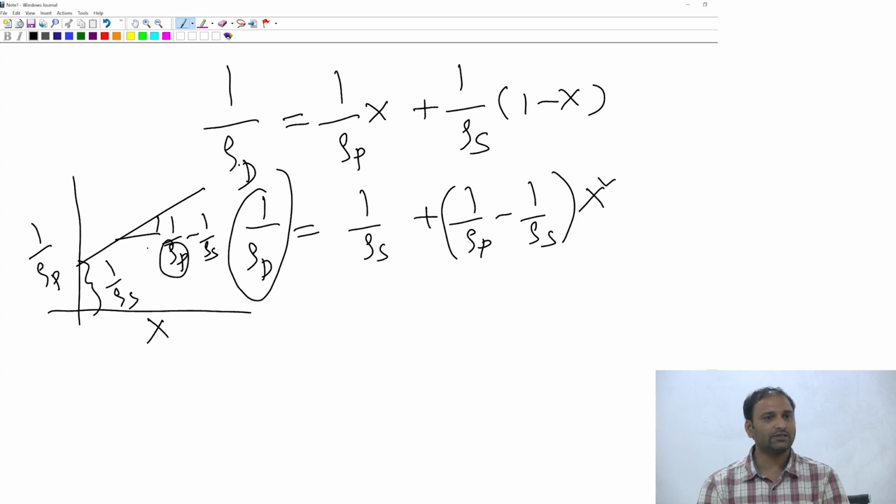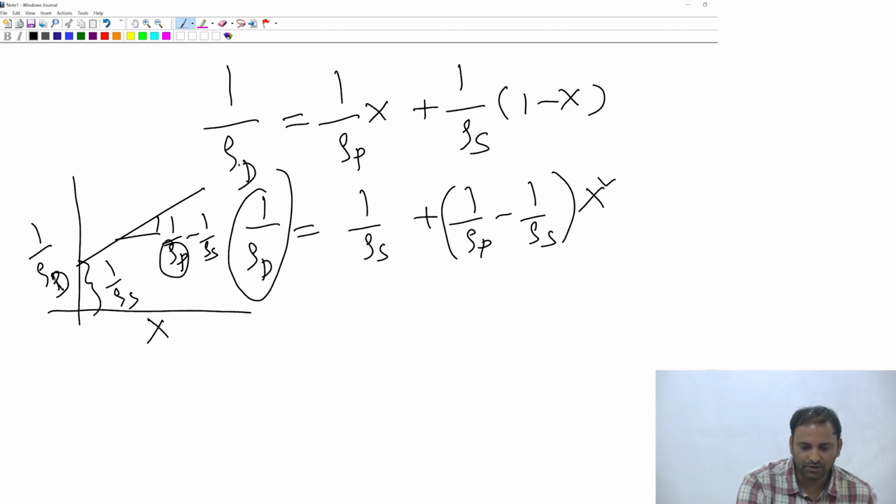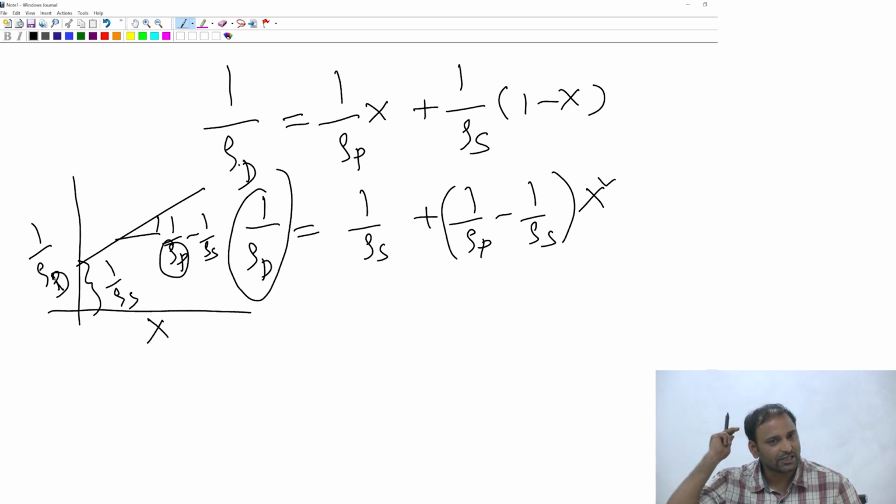What is being done is that you prepare a series of dispersions, 5 or 6 samples. I know the mass fraction of particles in each dispersion. I measure the density of each of these stable dispersions, and I plot 1 over rho of dispersion as a function of mass fraction. And just by measuring the slope and the intercept, I can actually calculate the density.